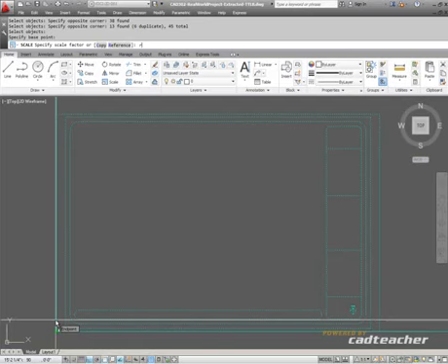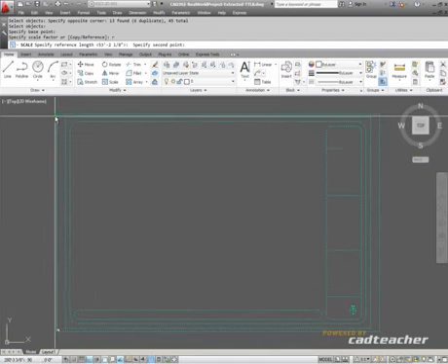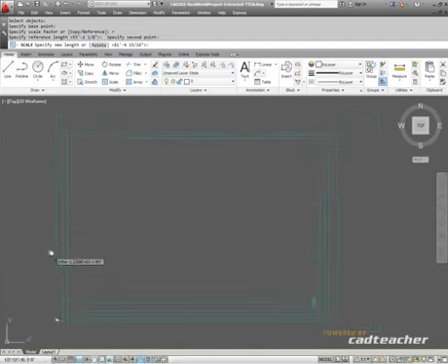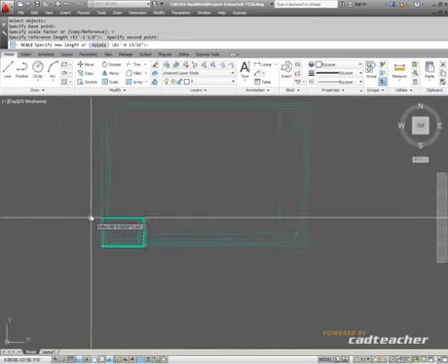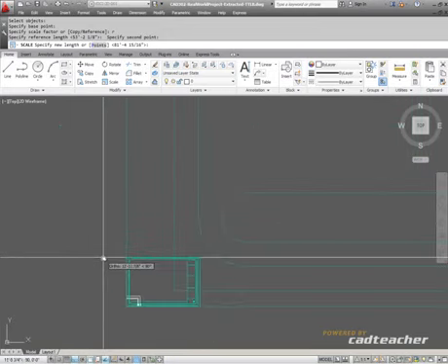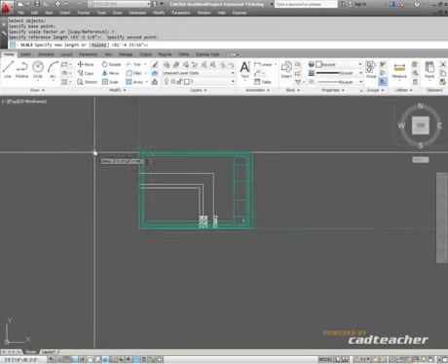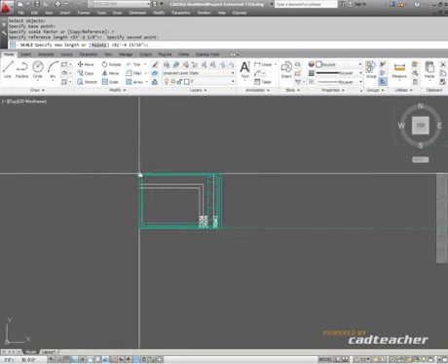And I'm going to do R enter for reference. My current reference length goes from the end at the bottom to the end at the top. You can see as I drag my mouse down, it's shrinking. I'm just going to zoom in, and I'm going to make the reference end go up to this corner right here at the white.